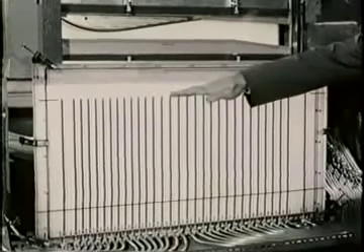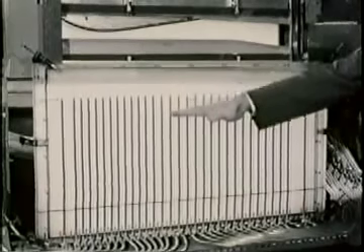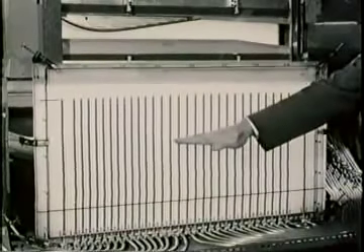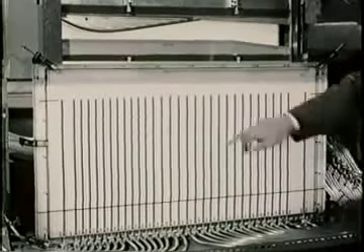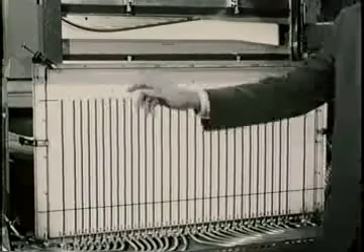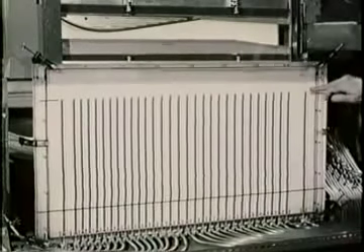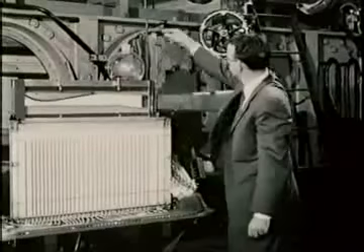Each column on this manometer board shows the static pressure at the corresponding point on the lower wall, the flat wall of the channel. We've arranged for the mercury level to go down when the pressure in the channel goes below atmospheric. Zero pressure is here. The first column always shows the stagnation pressure upstream, the pressure in the room. The last column always shows the downstream stagnation pressure, just ahead of the valve.